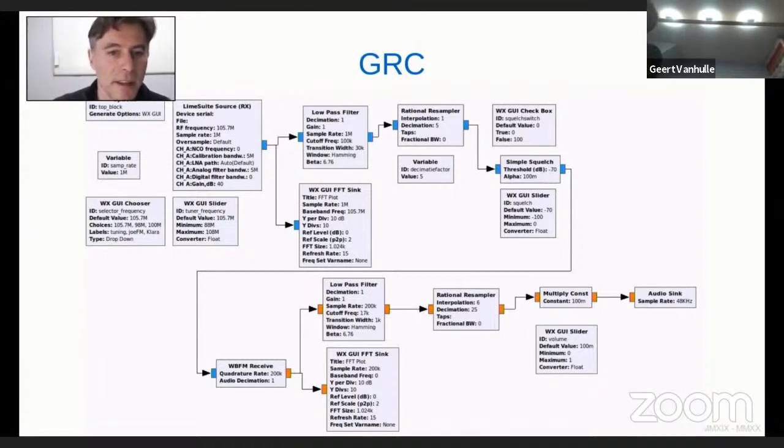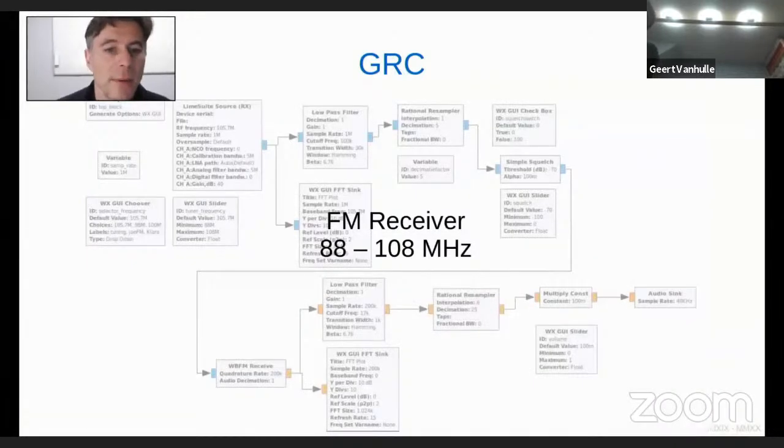And in this case, this flow graph is exactly the same as an FM receiver. So we have on the one side the digital samples, complex samples coming in, a certain bandwidth. Due to the processing in all the successive blocks, we will end up with a sample series going to the sound card of this general computing device that will produce an audio signal there exactly as a receiver would do, except that the whole processing now is done in a digital fashion.